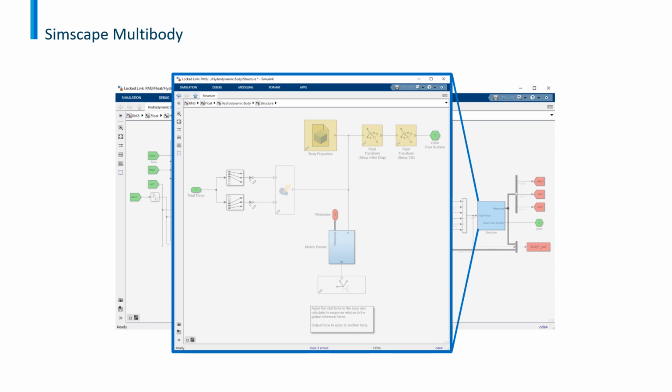In either case, the user needs to define the inertia matrices and if any initial displacements or changes in orientations are necessary. Once the body object is correctly defined, the wave class or the wave information is correctly defined, and the corresponding relationships between the bodies through the PTO and the constraint blocks are defined, the WEC Sim simulation can be completed. Thank you.